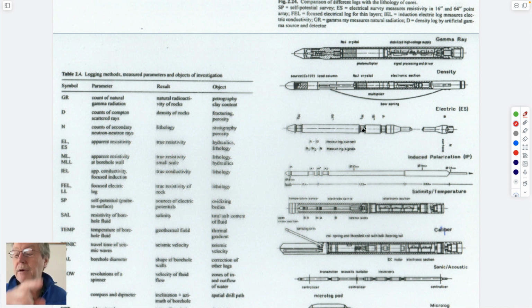You can imagine you could measure the electrical resistance between places. You can have radioactive sources in it to be able to measure backscattering of hydrogen nuclei, which represent moisture contents. You can measure the natural gamma ray background supplied to the sonde, which is usually a measure of clays, which have radioactive elements in them.